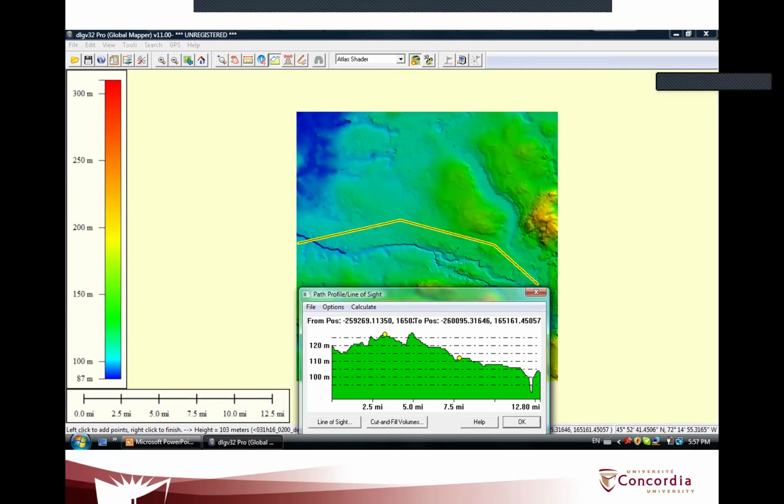This is a second alignment. So first alignment, second alignment. In this alignment, this is only the ground. This is only the surface. But it will tell you roughly how much you might need to cut and how big are the different movements when the highway is going to be constructed. You are going to have to cut and fill to even out the vertical alignment you have there with a vertical profile.